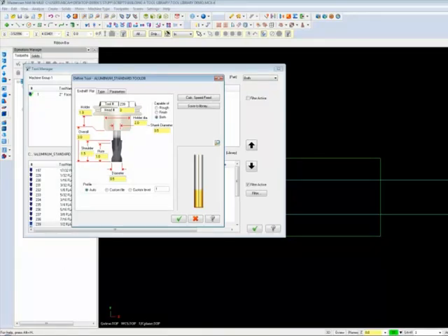The short end mill is assigned tool number 3 and has an overall length of about 2 1/4 inches protruding from the tool holder, a flute length of 0.75. Shoulder length may be different from flute length for certain tools, like our face mills, but since both shank and flutes are the same size here, it doesn't really come into play. When setting up tool lengths, be sure that the shoulder length is shorter than the overall length and longer than the flute length to avoid any errors.